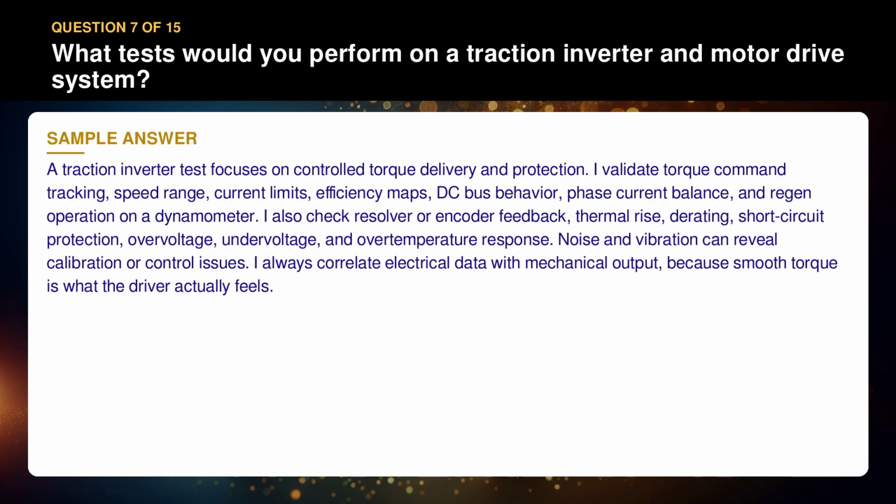on a dynamometer. I also check resolver or encoder feedback, thermal rise, derating, short circuit protection, overvoltage, undervoltage, and overtemperature response. Noise and vibration can reveal calibration or control issues. I always correlate electrical data with mechanical output, because smooth torque is what the driver actually feels.